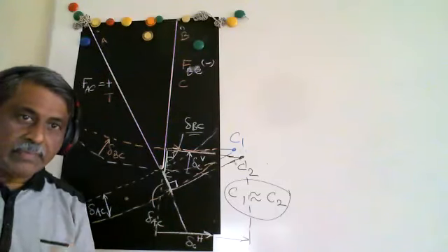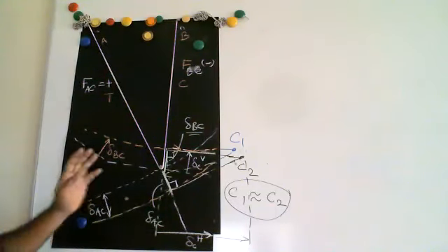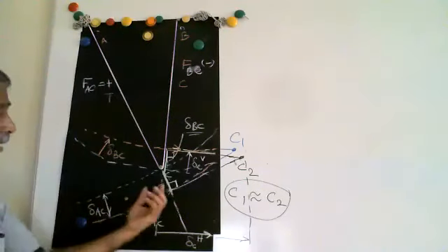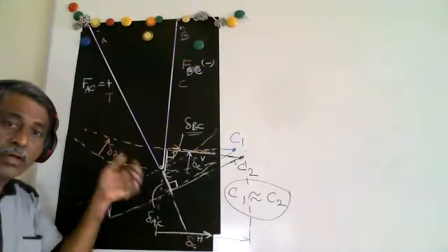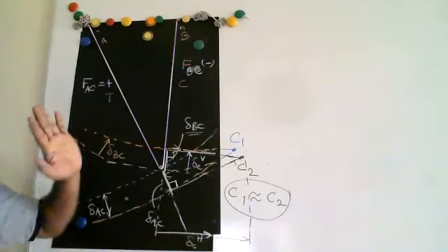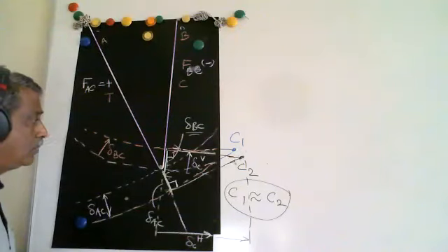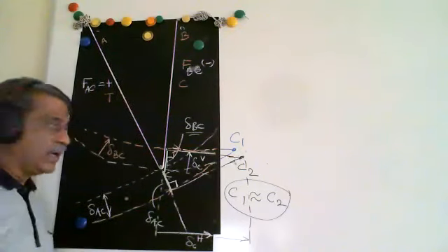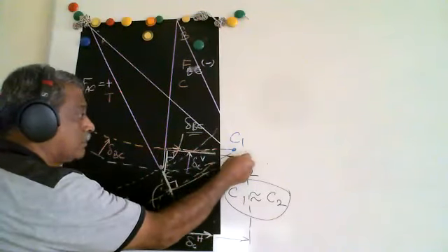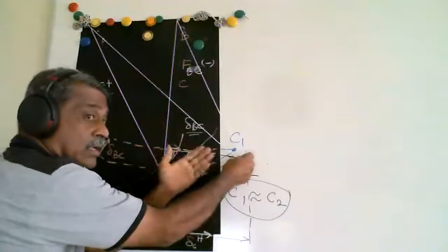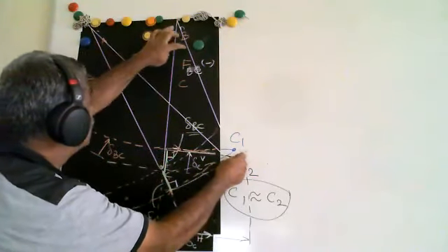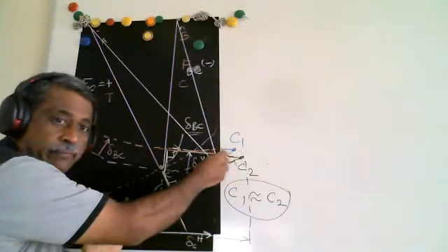So let me summarize. What we did was we said, okay, the lengths are very high compared to the deflections or elongations that the members go through. All these are axial members. Number two, since the lengths are very high, even if it takes something like this, of course I've drawn it magnified too much, this angle and this angle are small enough.